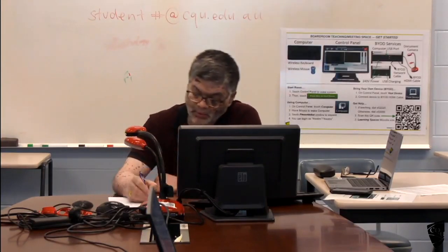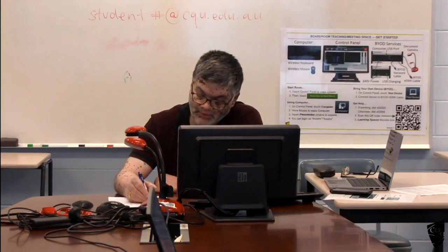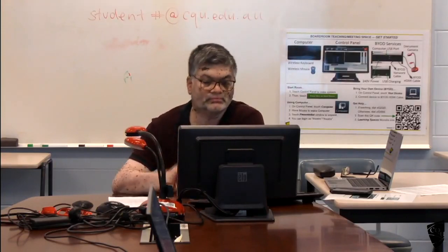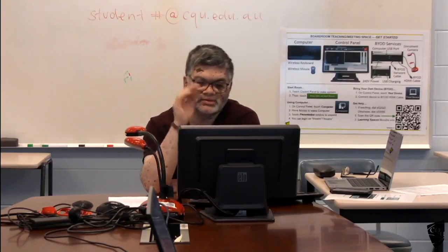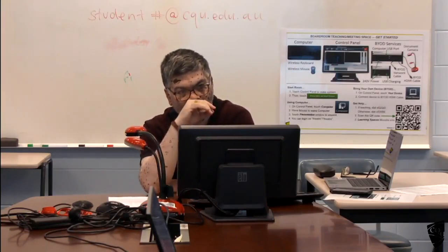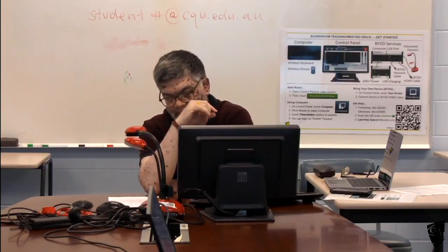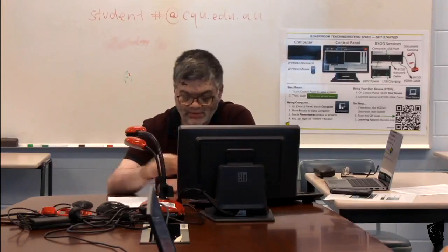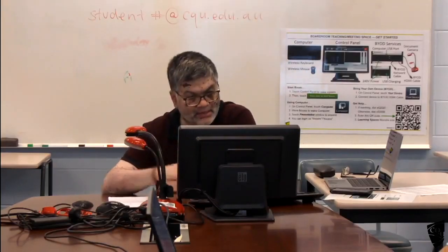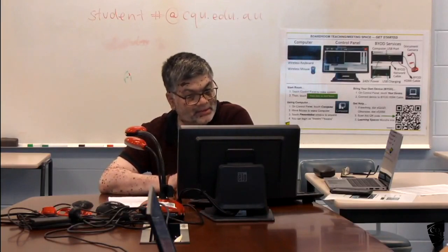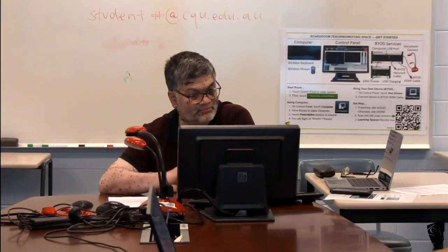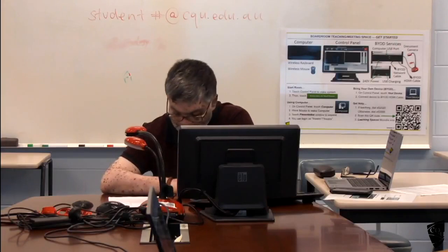So if you don't have beams, all the loads here will go to the columns. So the load transfer mechanism is a little bit different. The load will go to this column, this way and this way, both directions, but still it is not the same as what we learned for two-way slabs.